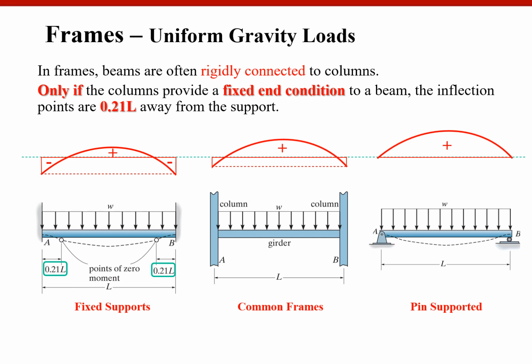But due to the moment resistance supported at a fixed or rigid connection, it will pull your bending moment diagram down, so that the maximum bending moment at midspan will be reduced as the fixed condition at the support location increases.